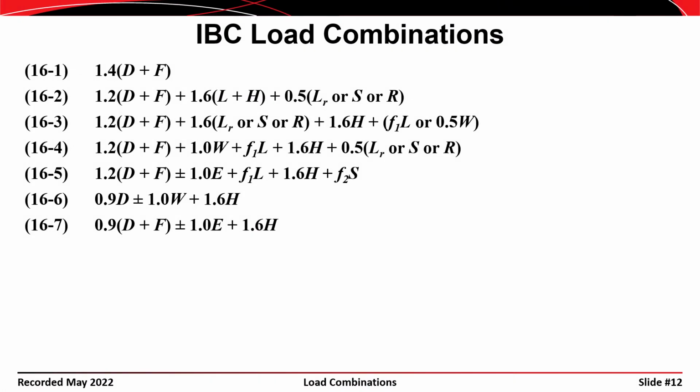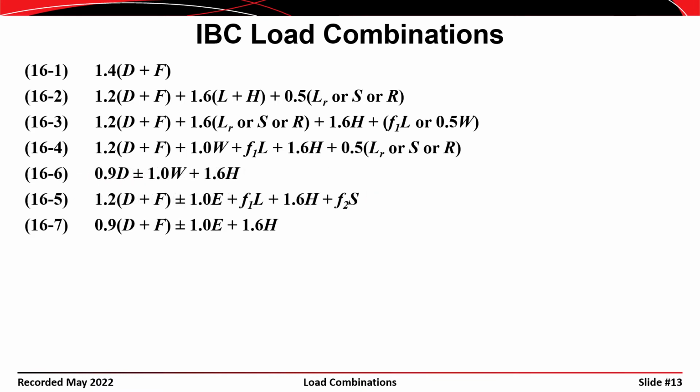All right, if we look at the International Building Code instead of ASCE 7, there is a set of load combinations there that at first appear like they are different. The first difference is that load combinations 5 and 6 are reversed. So the first thing that I'll do is I'll just flip-flop those and renumber it. Okay, after we renumber the load combinations, now at least they're in the same order. They have the same general approach, right? The dead load is the governing in the first. You have dead load plus 1.6 live in the second, dead load plus 1.6 times the environmental in the third,